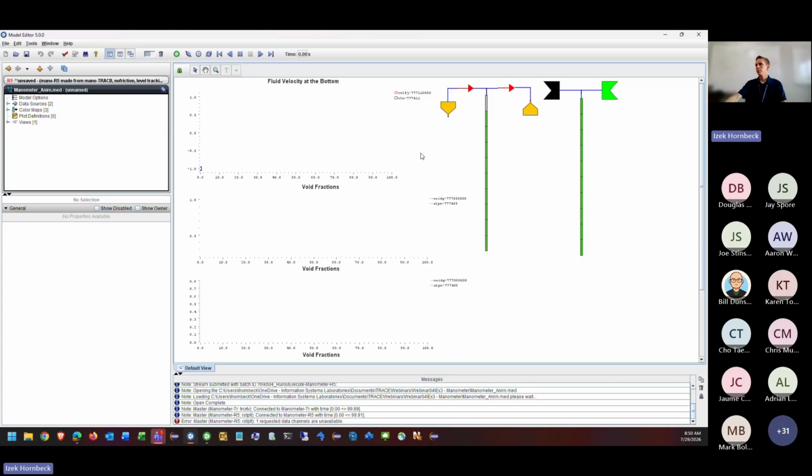So when you run it, at the turning points on the plot you'll notice that it'll run a lot slower just because of how tight it is there. But we can see with our red here, it's oscillating back and forth with that fluid velocity oscillating around 0. So it started at that -1 and increased to 1 and just oscillates back and forth like that. And you can see that the void fraction, the cell 5, is initially all void. It's all nitrogen there, no water, but it's oscillating back and forth right there. So we'll just pause that.